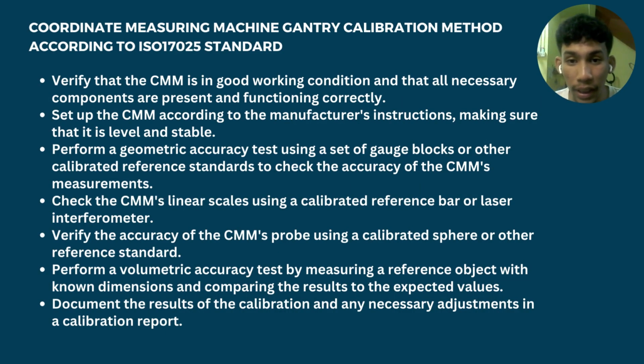So I will talk about the CMM Gantry calibration method according to the ISO 17025 standard. Firstly, verify that the CMM is in good working condition and that all necessary components are present and functioning correctly.